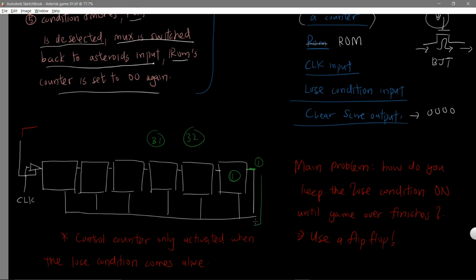So it goes and activates the reset input of every flip-flop. Once this reset input is activated, every flip-flop is turned to state 0, and it will start from 0 to 31 again and reset on the 32nd pulse. Then that is our mod 32 counter.